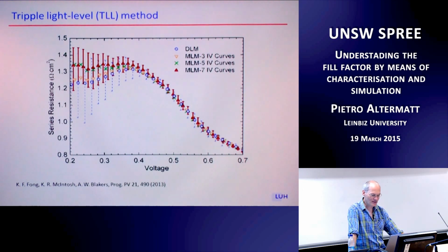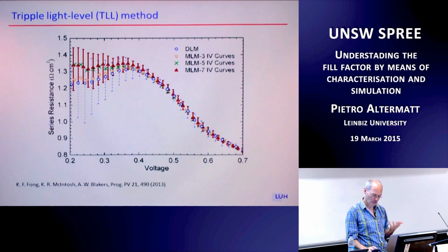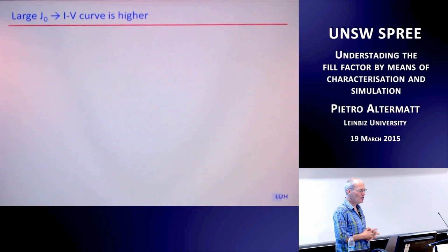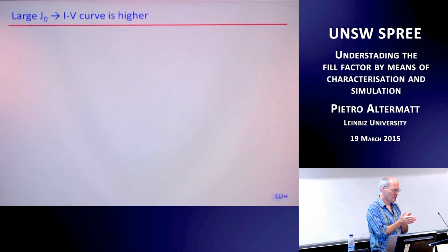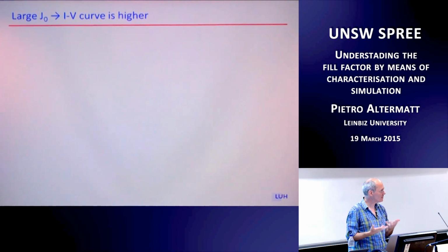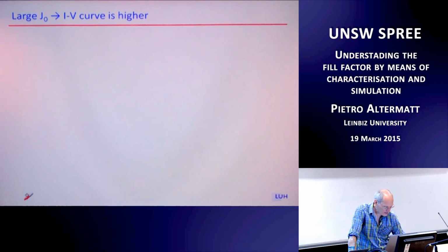But as I said, important is the fill factor a little bit below MPP if you work in a module, and between MPP and VOC if you actually want to analyze the fill factor. So this brings me to the next thing. Once you got RS, what about the ideality factor? How does that connect with anything in the cell? And I better draw this.